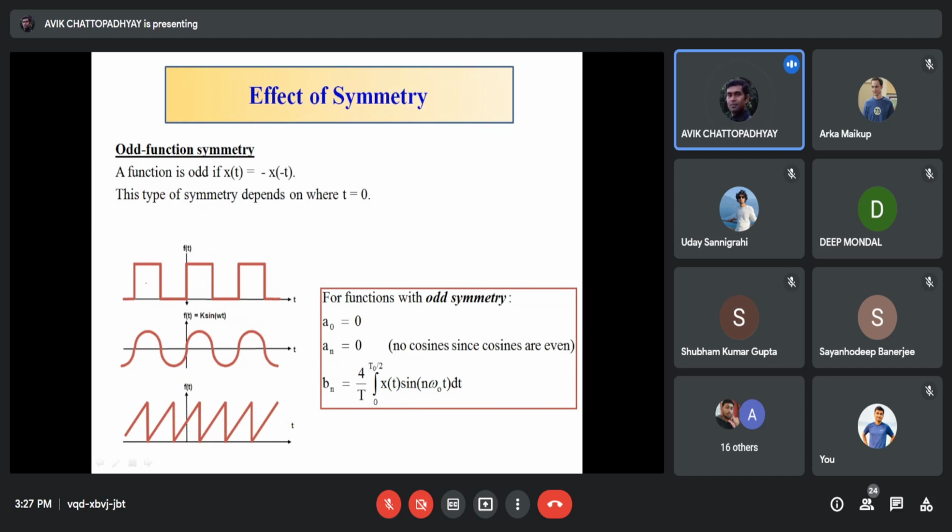How? You should understand the odd signal. To get this odd symmetry, the signal or the function has to pass through the origin. There is no alternative. By virtue of its nature, it has to pass through the origin if it has to be odd. So obviously the DC term will always be 0. The area of the positive half and the negative half will always cancel.